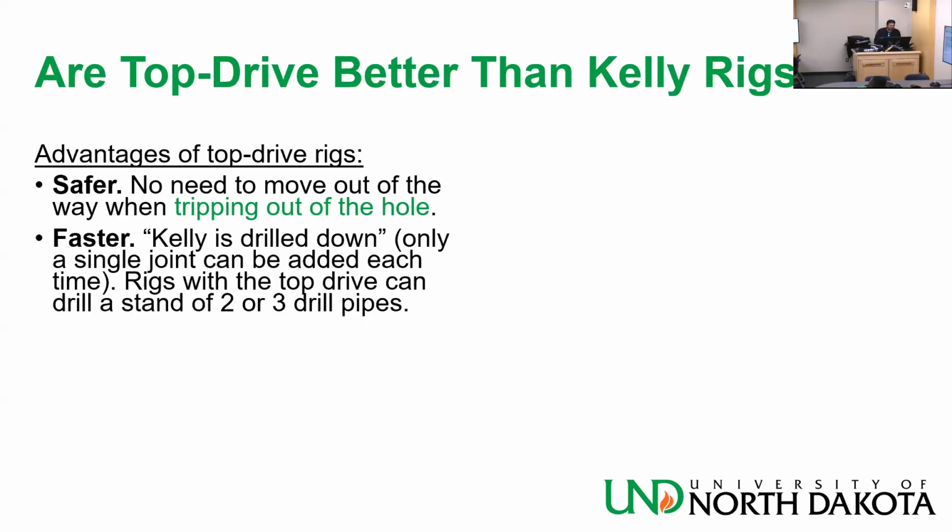Okay, it's faster. Kelly is drilled down. It means that you reach the bottom of that. The whole Kelly was drilled, was 40 to 54 feet. So you need to basically shift it up, take it out, put the new joint in, make the connection, and then start drilling again. Now, you see only a single joint can be added each time. Rigs with the top drive can drill a stand of 2 to 3 drill pipes. This is not always the case.